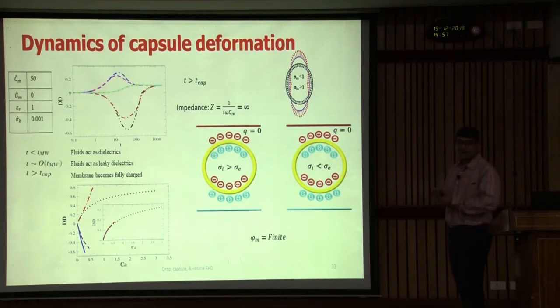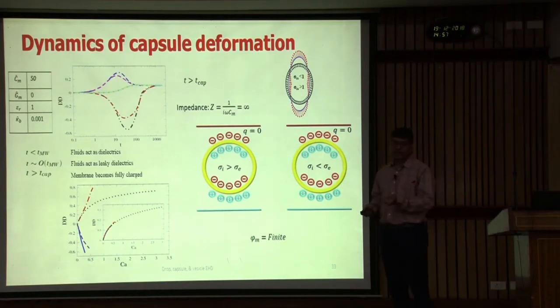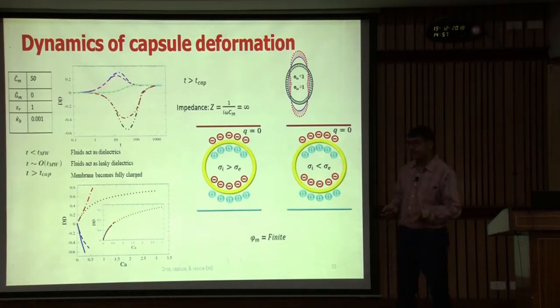Okay, there is some complication with the Maxwell stress. You actually have the Maxwell stress as normal electric field squared minus the tangential electric field squared, and because the normal electric field is 0, it's only proportional to the negative of the tangential electric field squared. It's kind of not very intuitive. You have tangential field which causes the normal stress, but the tangential stress is 0.